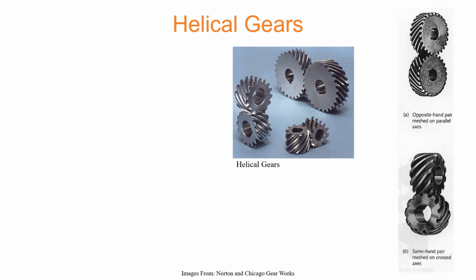So the other type of gears is called helical gears. The term itself comes from helix. It is a word derived from the helix. If I just make you recall once again, we're going to have this as the axis of rotation, and about it a helix of this kind constructed. And because this tooth profile is following a helix, these kinds of gears are called helical gears.